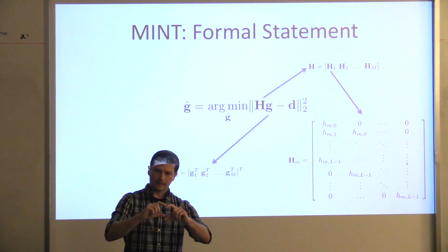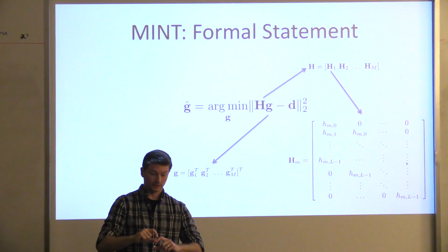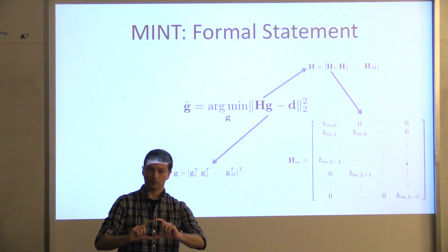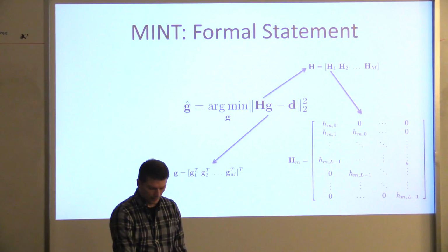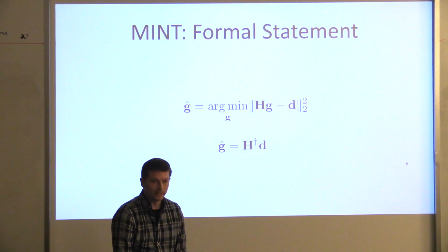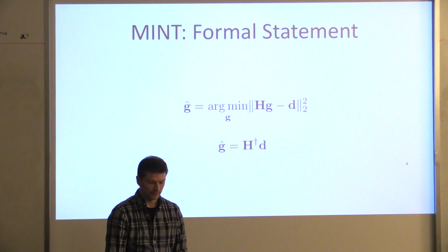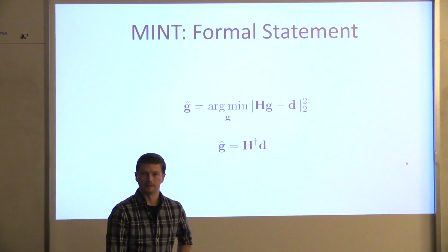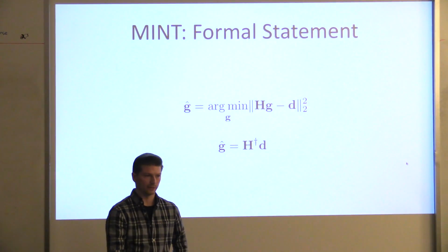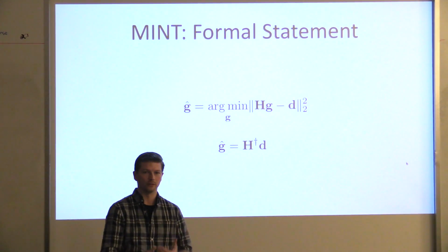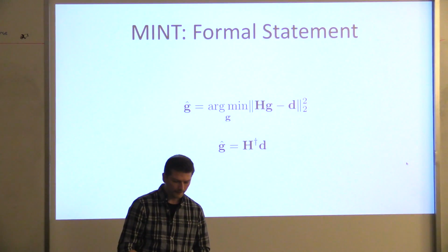Similarly, we've stacked the filters G that we're trying to design. These are column vectors that have been stacked together into one big long column vector. And then we can very easily find the solution to this just by taking the pseudo-inverse of this matrix. So at least we can get a solution in a closed form way, and we can do this very quickly. There's no need to do a kind of adaptive solution.